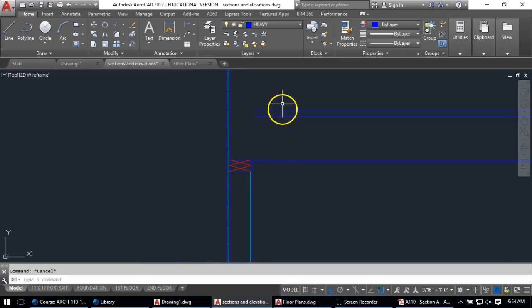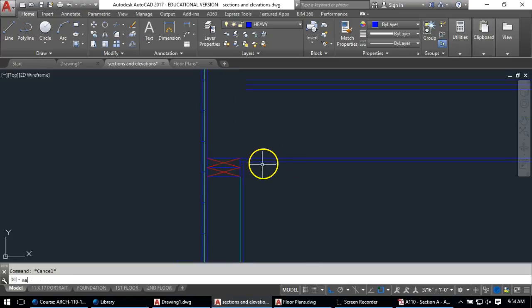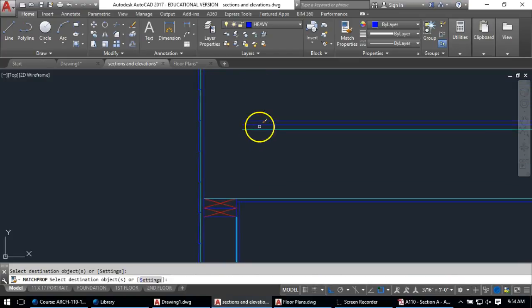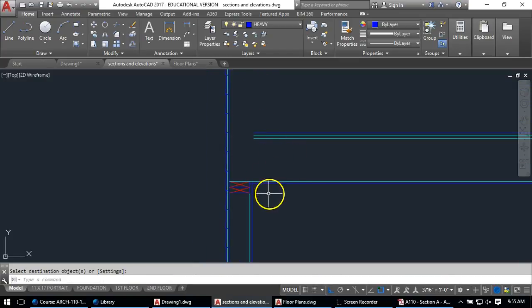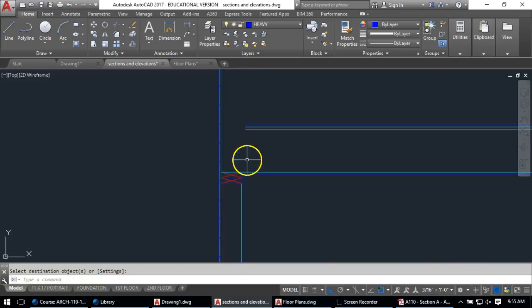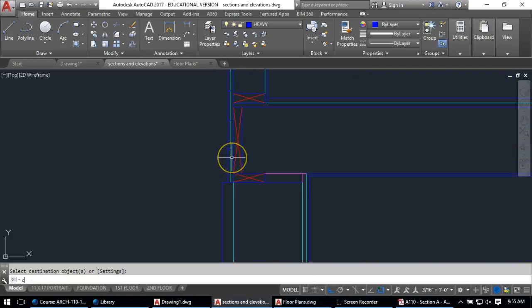Again, what I'll do is, now this is a big gap here. That's my joist. And my joist technically is a light line weight, but I got the gypsum on one side and the sheathing on the other, so I'll turn all these sort of internals to a medium line weight, and it's sort of the exterior. This line and this line is sort of what you would see as a person, so I'll keep those as a dark line weight, and we've got the same 2x12 and plate sort of going on.